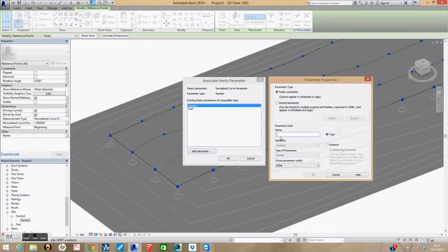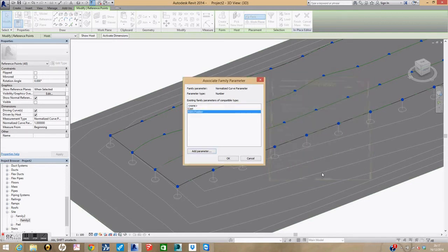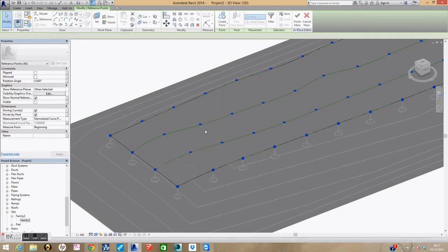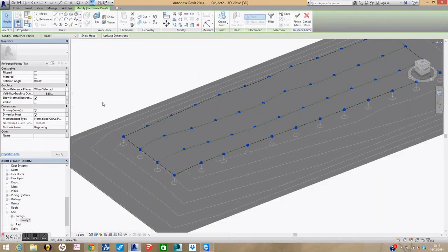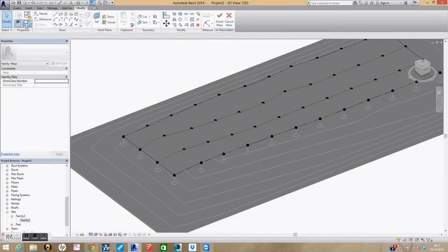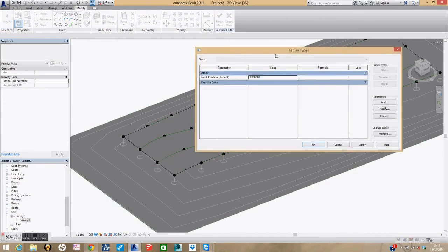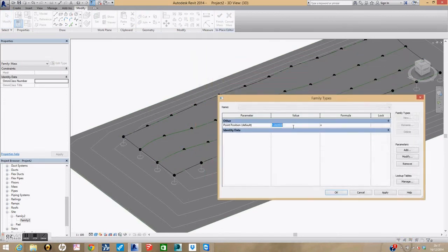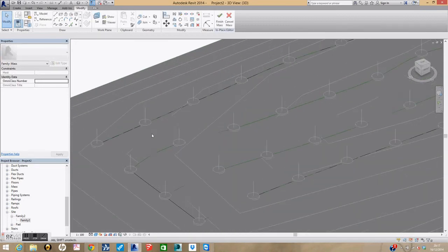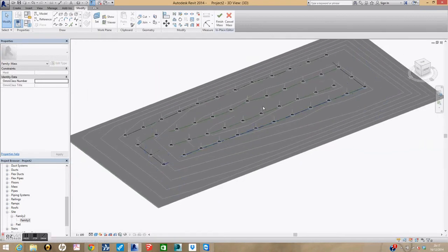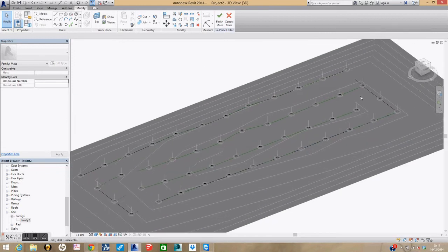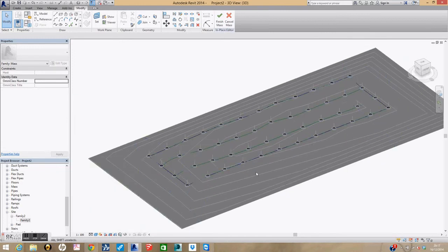For those of you who are now confused, that just means I can push it. If I set that to 0, I can push it right down on top of the surface. So essentially what I've created is a mass surface that relates itself to the topographical surface. So if I change the topographical surface, so does my, call it my tissue paper that sits on top of all my little masses.